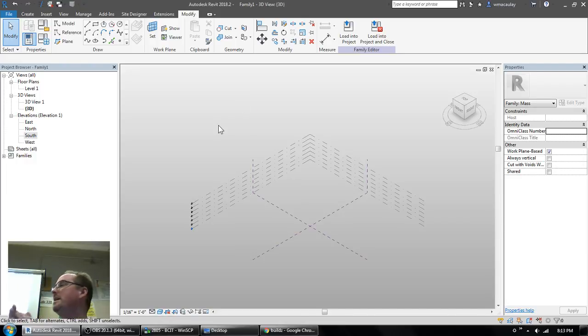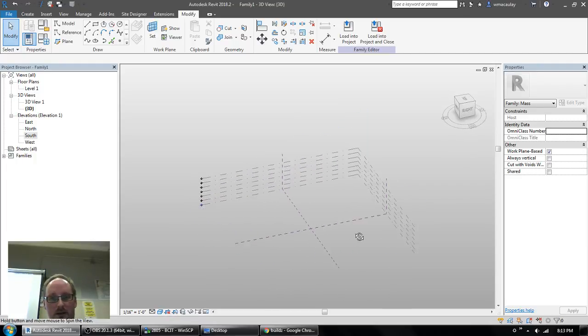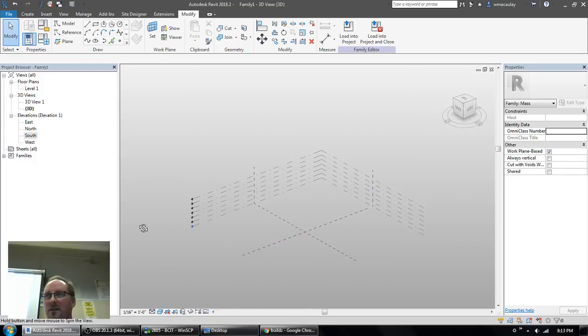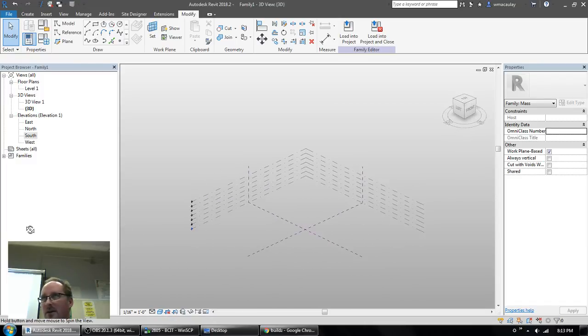When you go back to 3D in the Conceptual Mass environment, every level that you create appears in the 3D view. Weird, eh? And watch what happens when you orbit. It shows those levels kind of at the back, like there's this invisible box that has the levels just printed on the inside of the box. So the idea being that you can start to create forms on each one of the different stories of your building, and this can be used to generate a shape for the building.